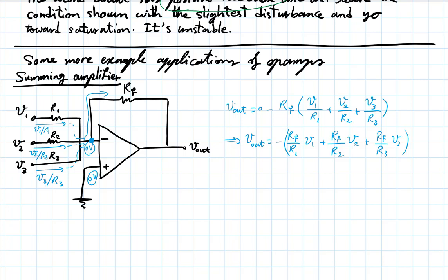So you have your least significant bit and most significant bit. And if you have a byte with a number of zeros and ones, the first bit on the right-hand side will be just 0 or 1. The next one and the next one and the next one will progressively represent higher powers, right? So have these ratios of resistances correspond to those powers. And then when you add these, and if your inputs are those digital signals, 0 or 1, your output will be an analog that corresponds to that digital signal.